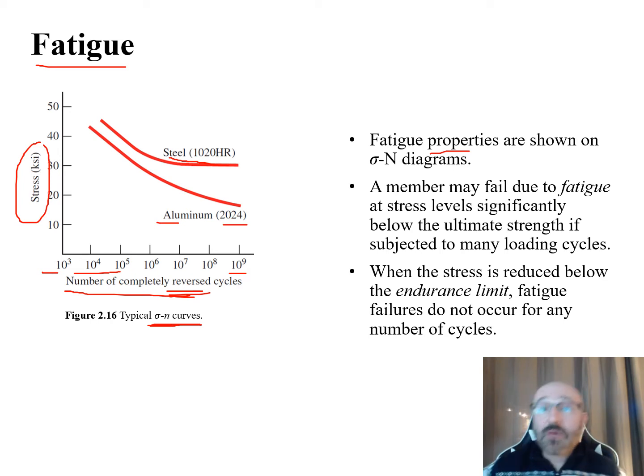Now, something to consider with fatigue testing is this is a real-life practical application. People are going to be using this over and over and over again. It's not going to be used once with hope that it doesn't fail. So a member may fail from fatigue at stress levels that are significantly below that ultimate strength, if it's subjected to a certain number of loading cycles.